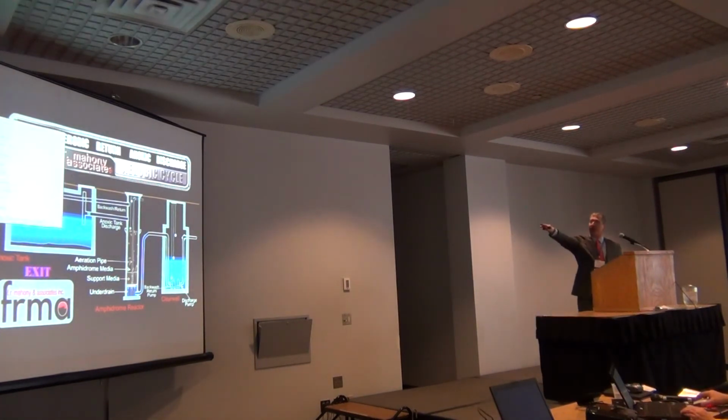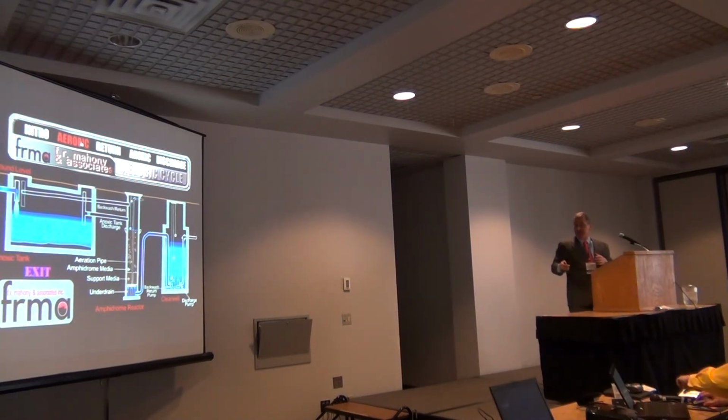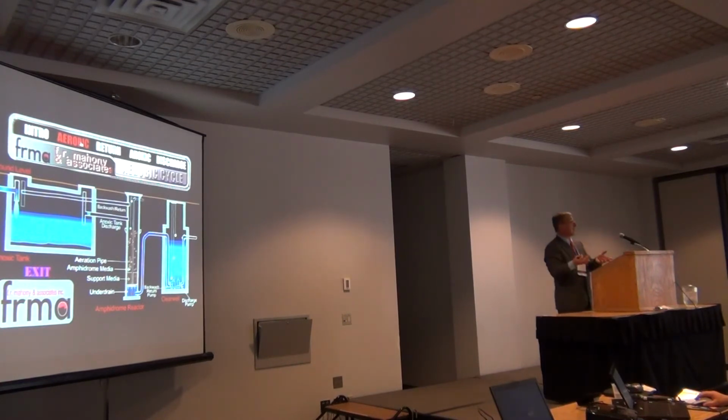So in the first part of the system, we have the wastewater flowing into the main tank, or the first tank, and then the supernatant will overflow to the filter. And we're aerating from the bottom up. And the wastewater is flowing down through the sand. And when it goes through the reactor, it actually flows through this pipe, through this pump, which is off during forward flow, and it fills up the clear well. So during this phase, with the air on, we're trying to oxidize BOD and nitrify.